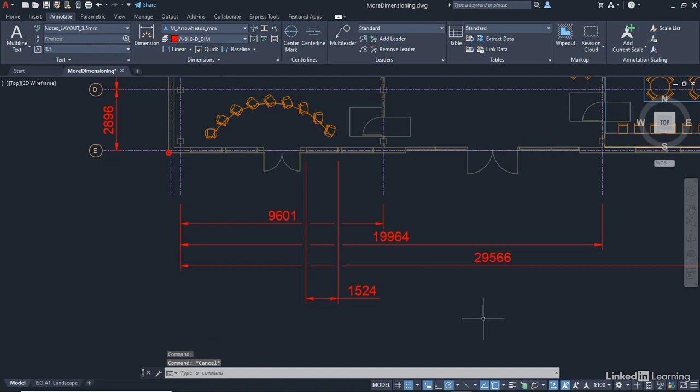It also tidies up your drawing because now it's obvious that the 1524 is the window dimension and the other three dimensions are separate to that. Because where the extension lines and the dimension lines cross, you can easily miss an arrowhead and the dimension could then be incorrect on site when you're building this building that we've got the ground floor plan of.